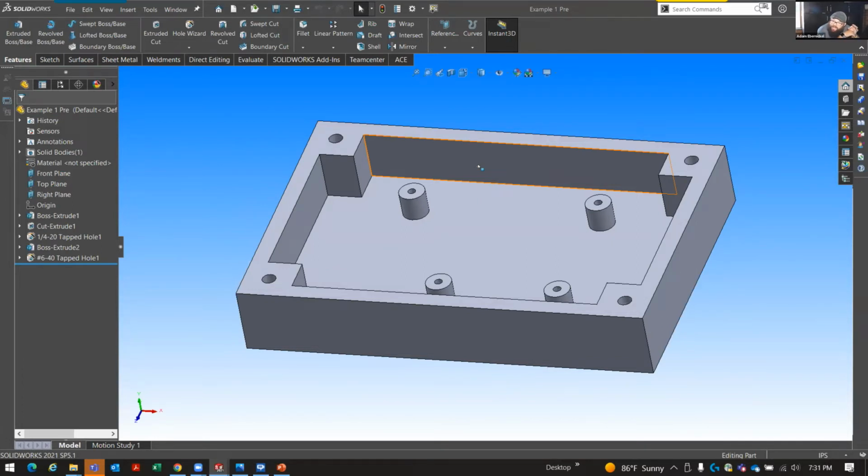It's a half inch diameter, so that'd be a 1/4 inch. So you would think logically we could do a 1/4 inch radius to get our finish on the verticals. Now, if it's a ball end mill, we might be able to get those radiuses on the bottom. If it's a flat, no. Correct. The good thing about this is you're going to have to start working back and forth with your machine shop, figuring out what the capabilities are.